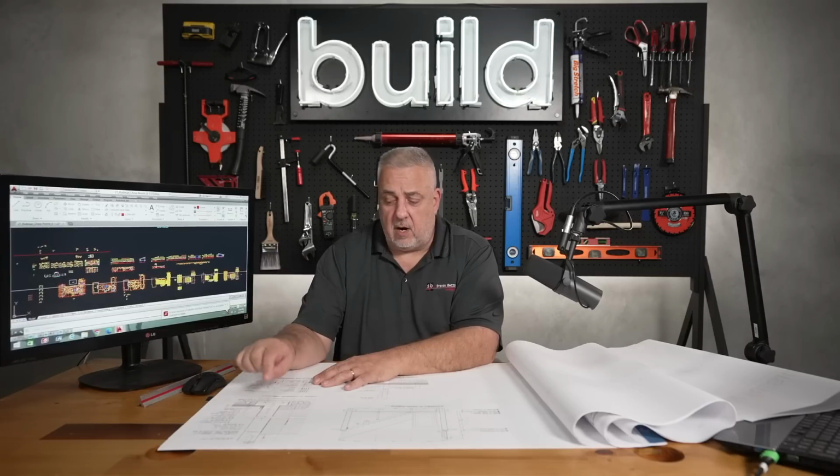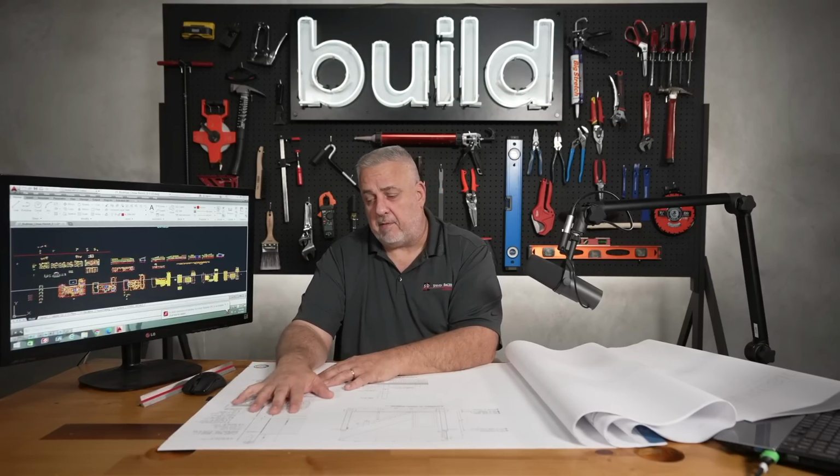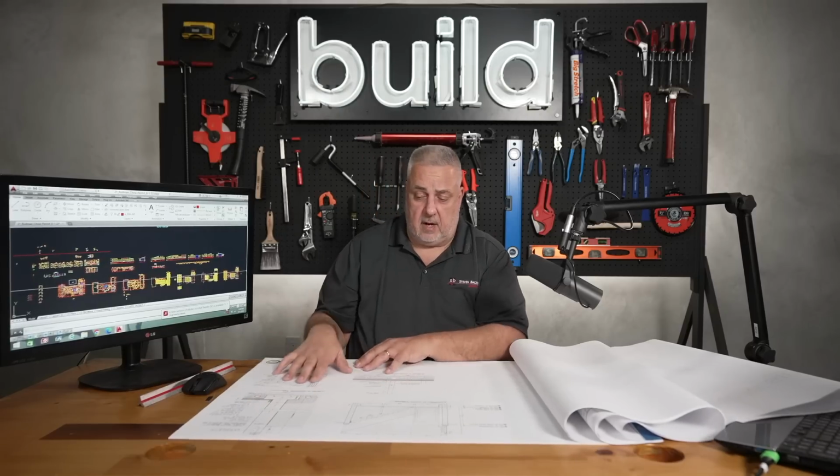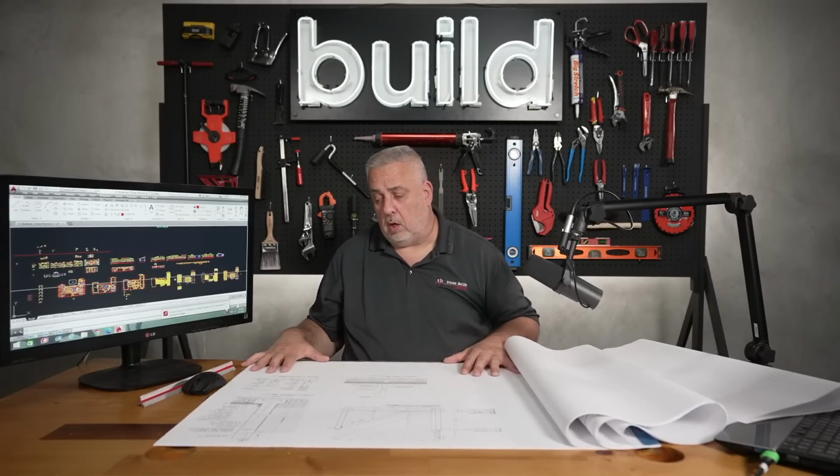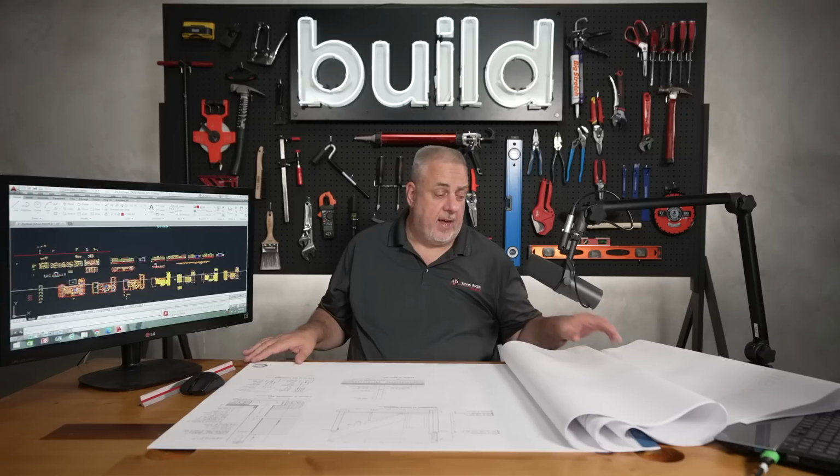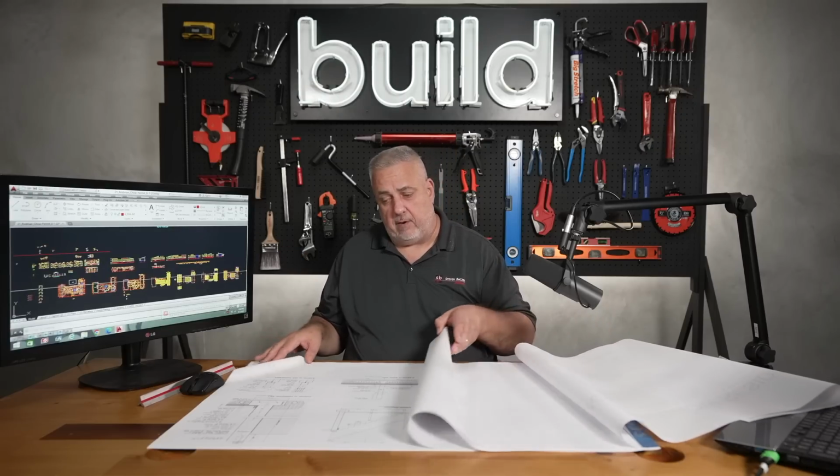Foundation guy cares about the foundation. So I give him a foundation drawing. It has the rebar in there. It has the drainage and everything that's going to happen associated with that floor plan or that foundation wall of the basement. And we put that there, and I strip out all of the other information.